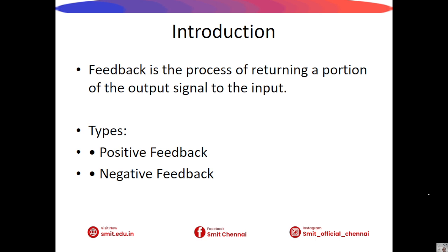First, we see about the introduction. Let us begin with the concept of feedback. Feedback refers to the process of returning a portion of the output signal back to the input of an amplifier. There are two main types of feedback: one is positive feedback and the second is negative feedback. In positive feedback, the feedback signal is in phase with the input signal. In negative feedback, the feedback signal opposes the input signal. In amplifier design, negative feedback is preferred because it improves stability and reduces unwanted effects. Throughout this lecture, our focus will be on negative feedback only.